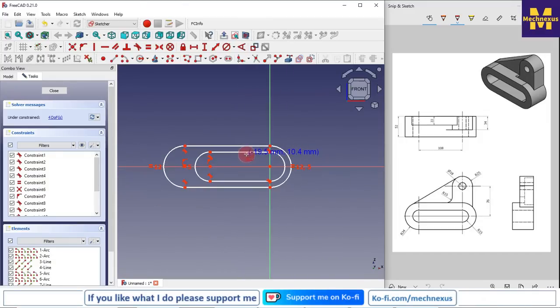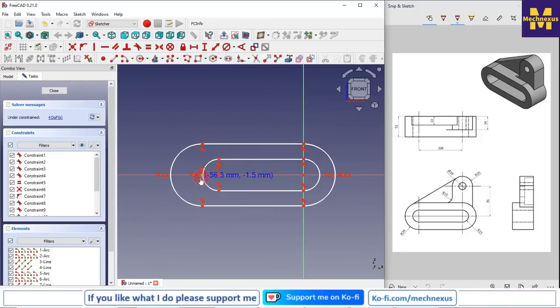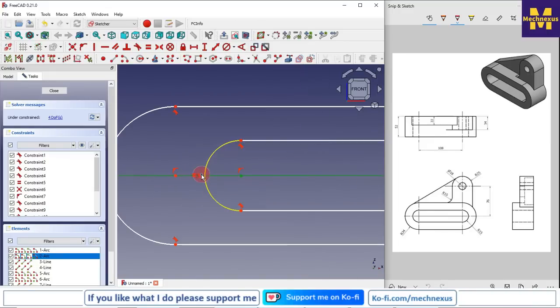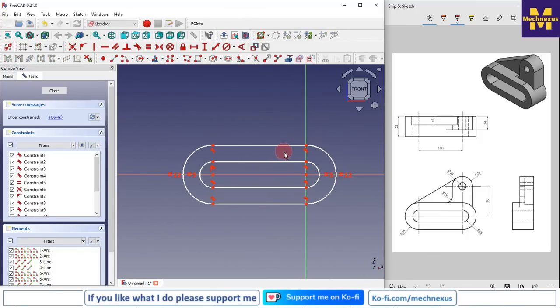and now we will constrain these two slots. So if I move it, then you can see that it is symmetric, but it is not constrained, so we will constrain it. I will select the origin point and this point and say the merge, this and say the merge. And now we will give the dimensions.